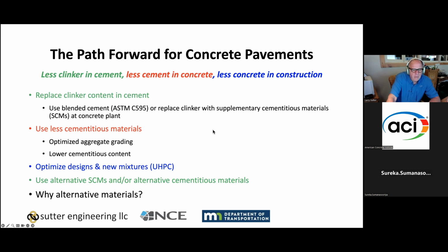The approach here is really to optimize your concrete mixtures, optimize the aggregate structure, and get to the lowest possible cementitious content that you can to still attain the same performance that is required for the structure. There are new things we need to start thinking about. We need to start thinking about optimizing how we design, and we need to start thinking about using new concretes to allow us to do that.